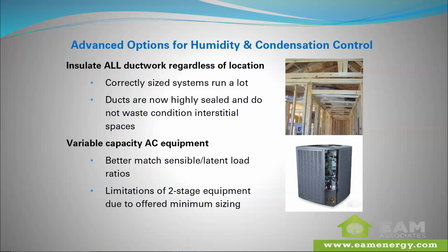I will note, we are talking about variable compressor, variable speed condensers here. The variable speed furnace is not really helping you in this particular regard that much. And actually, we don't have time to go into it, but in some cases it can kind of hurt you a little bit. Be aware that really fully variable equipment, or at least many multi-stage equipment, is what's needed if you want to use this as a solution.